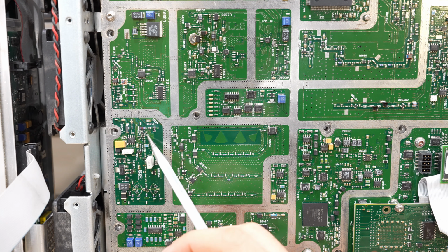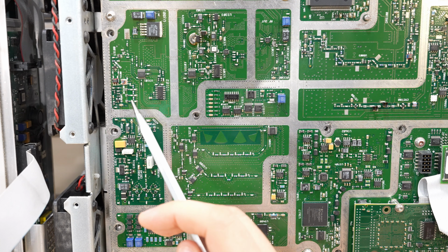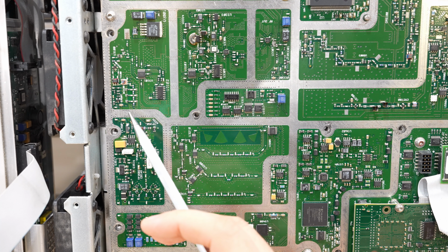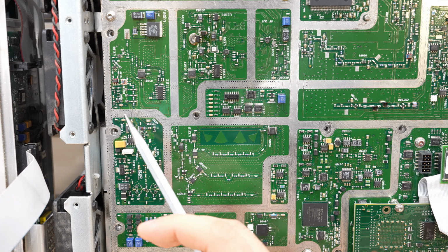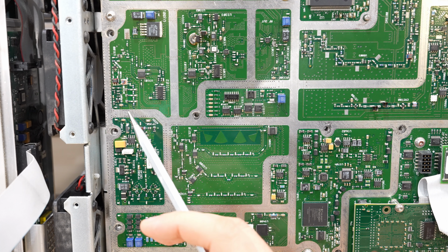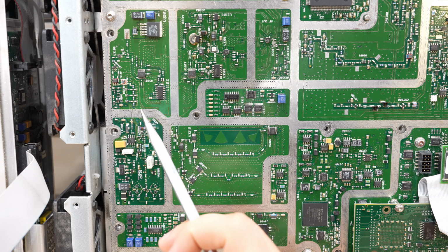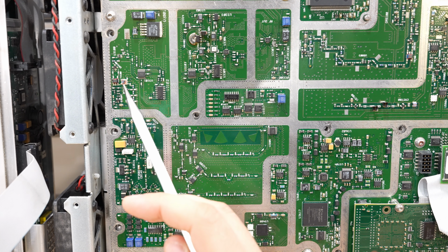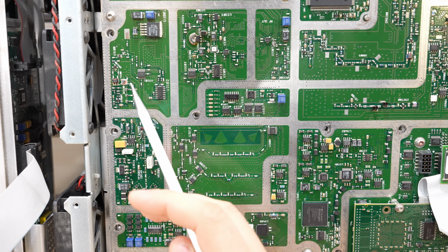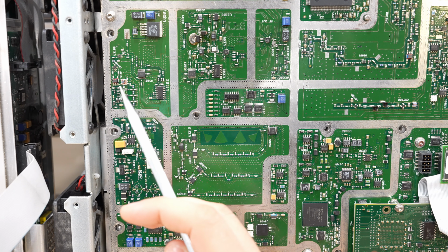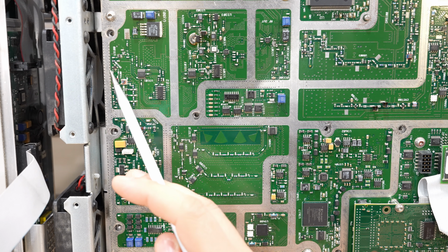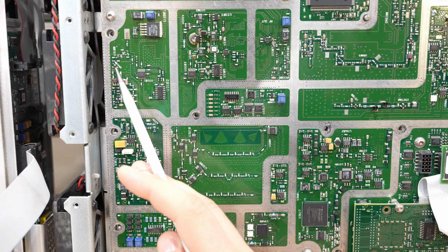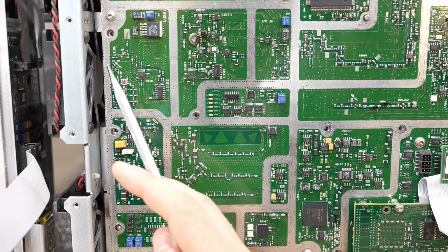The output goes over here. There is an amplification stage and then it jumps to this section. And if you remember from the block diagram, here is where they split it off. So one goes off to get divided for the rest of the frequency, and the other one actually gets doubled as part of the primary path of the fractional-N as well as the actual functions. And I think that doubler is right over here. We can see that they steal some power using a pair of these transformers, so they basically couple some away. And then at this point, it looks like they're differentially driving this, maybe just a diode actually, creating the double signal. And then what comes out is single-ended.